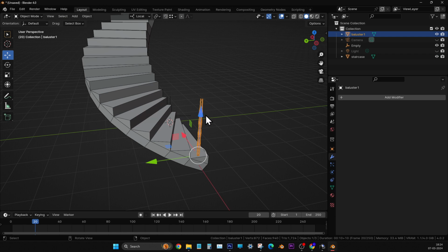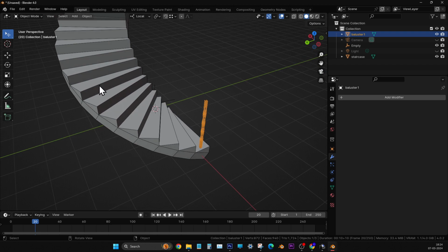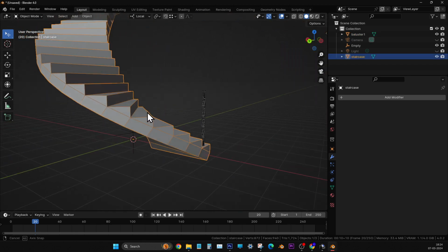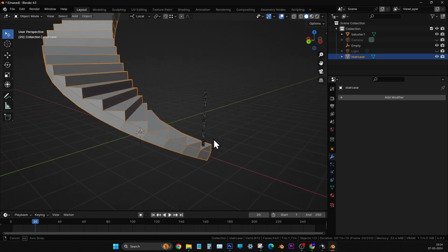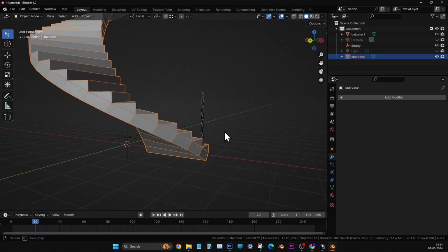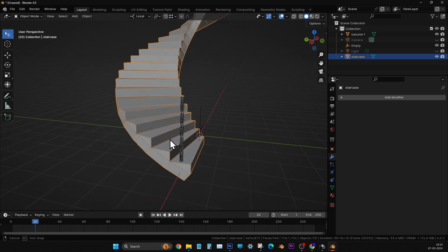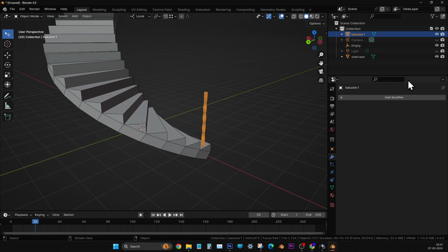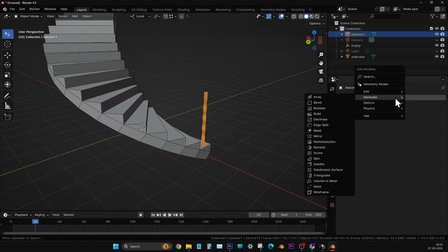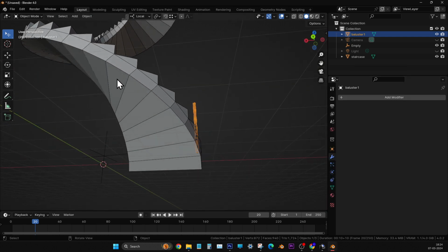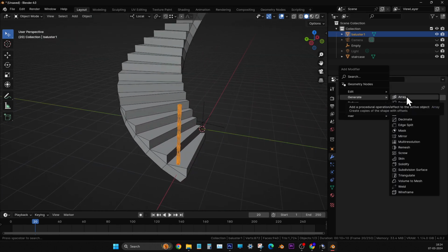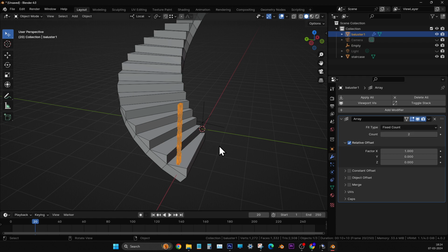So select the baluster first. Baluster is the slave, the junior guy. The staircase is the senior. He is having the... oh, we actually applied it, no? Okay, right. Applied. So we have to give it manually because we applied. Actually we should apply later only. But to create the thickness we applied, it's okay. Now we'll go to add modifier and apply array.